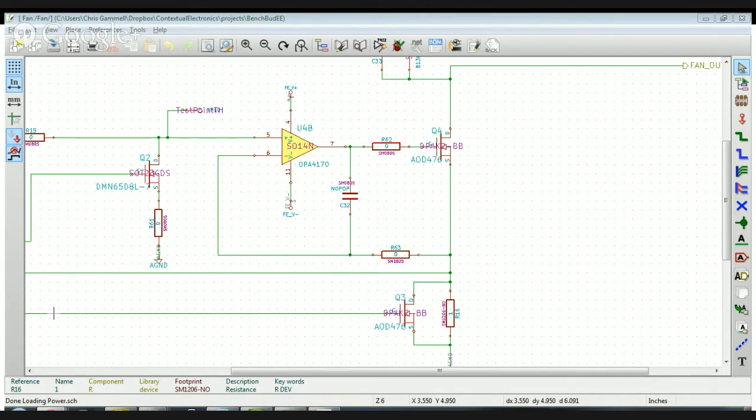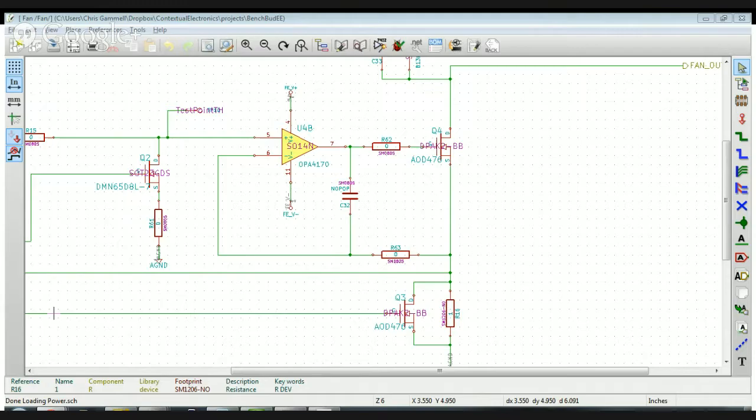I had a little problem with driving little current through the Q4. It will get pretty hot, and it will trigger the PTC, which is right under the Q4. So the board gets hot, and the PTC will trigger much too early. I am thinking of putting some kind of standoff between the board and the PTC, like bodging something in there to raise the PTC out of the board.